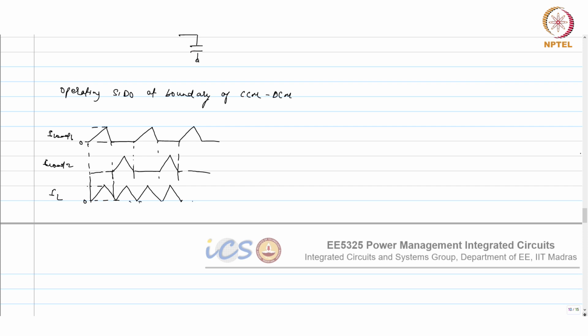So there is no time during which you have a high Z region. So the inductor is not resting. As soon as the inductor reaches 0, you trigger the other phase. But the problem with this is that frequency will vary. When the load current changes, or when input or output is changing, your slope will change. So it may reach the 0 point at a different time. The same may also happen if your load current is changing. So in order to maintain this continuity, you have to change the frequency.